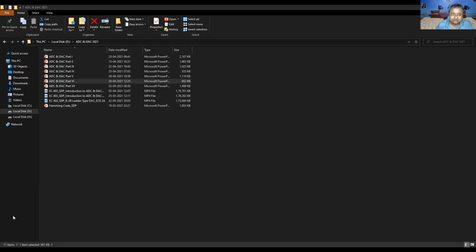Okay. So during this time, the counter gets advanced and it will count again. When V1 reaches 0 volt, the comparator output will become 0, because this is one positive ramp. So this becomes 0. So the clock is inhibited from passing through the AND gate.